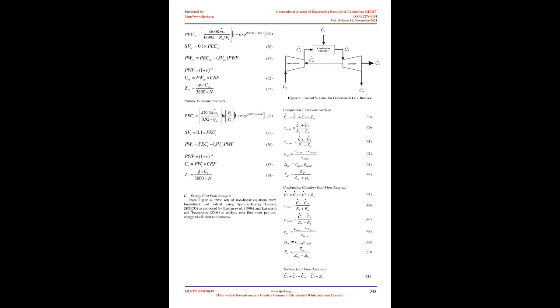2. Materials and methods. A. Description of plant investigated. Figure 1 shows a schematic diagram of the system under investigation. A 180 MW single-shaft Alstom GT13E2 unit gas turbine power plant located in Afam, Rivers State, Nigeria. A 5-stage turbine and a 21-stage axial compressor installed on the same shaft serve as the primary mechanical components, as does a combustion chamber between the compressor and the turbine. At a rotor speed of 3000 rpm, it has a maximum combustor temperature of 1368 K, a pressure ratio of 16:1, and an exhaust flow of 528 kg/s.